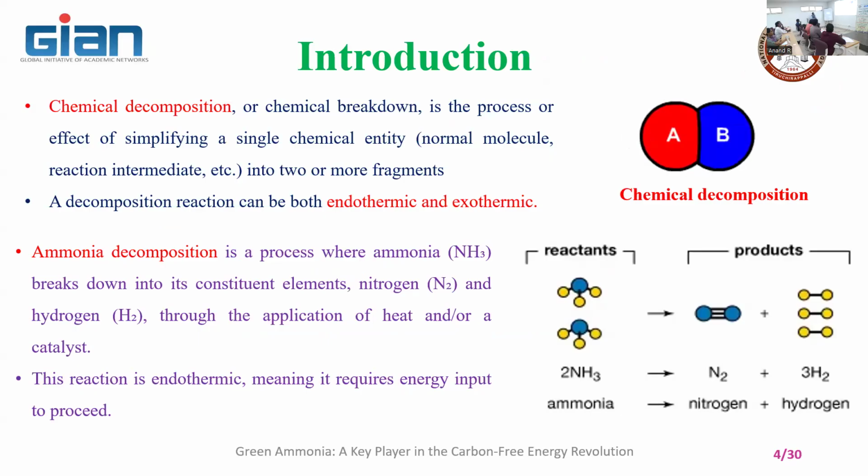So decomposition is nothing but the breaking of a molecule, an endothermic process. So you are going to break the ammonia into nitrogen and hydrogen. You may have come across different lectures from D1 to D8 on how to produce ammonia from different sources, or from electrolysis. Then whenever there is a necessity for hydrogen, either for an internal combustion engine or the fuel cell, you can employ the decomposition method of ammonia to bring the hydrogen. You can even generate the hydrogen on board. So that is the advantage of carrying ammonia instead of carrying hydrogen, particularly for automobile systems.